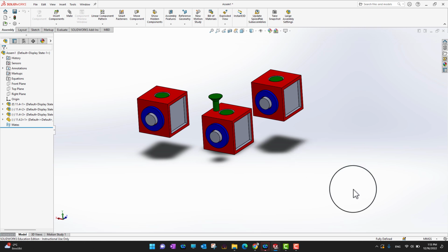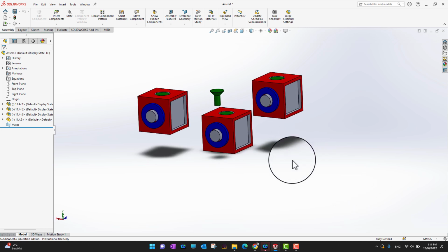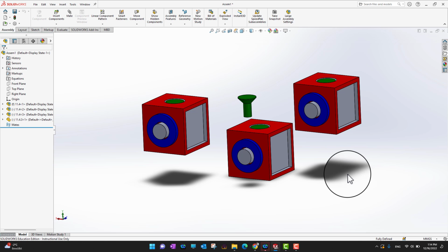If you have to do something multiple times, you can make it into a sub-assembly, then create multiple sub-assemblies, and then you can just modify your parent sub-assembly and it's going to apply to all the other sub-assemblies as well. So this is a really powerful tool in SolidWorks, and you should try it in your designs. In the next video, we are going to learn how to apply linear and circular patterns in assemblies, if we need multiple patterns in the assembly.